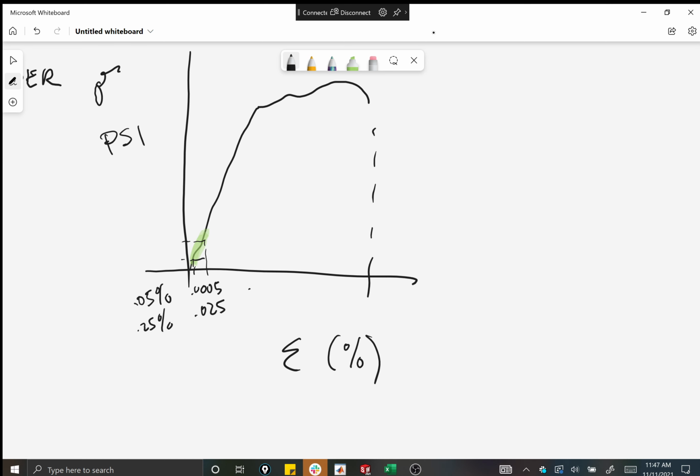That's true, that's definitely true, but that's more up here, right? What I'm trying to get at, and this is a fine point, and nobody got this right on their individual assignments: we measure this at this point because the further we stretch it, even though this is supposed to be a straight line, the second we start stretching it out, it's going to get thinner. It's going to have less area, and therefore that's not going to be a straight line anymore.